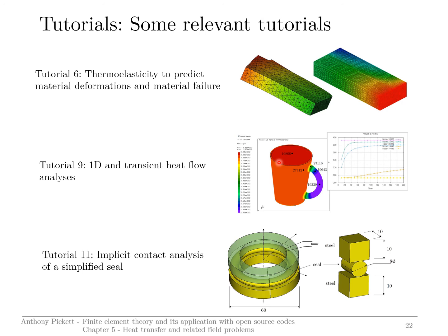So in this case, we include this term of the capacitance and density of the material in order to predict how the hot water transfers heat through to the handle. And you can see the fast heating up, which takes place at nodes very close to the hot water, and the slow heating up, which takes place at points on the handle where it's being held.